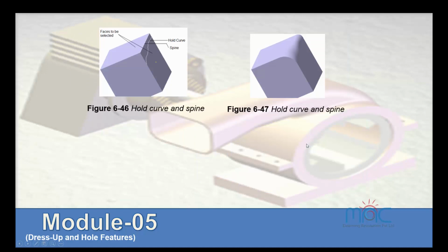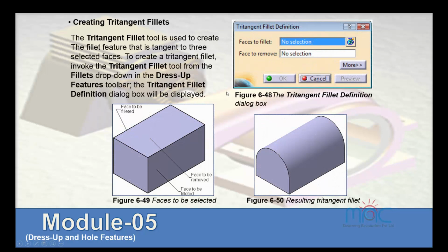And here is a little bit advanced option where the curve is the primary dominant for controlling the contour of the curve and the shape of your particular fillet. The fillet radius is controlled through the curve when that is applied. And in very typical cases, you can use it. You do not get a bunch of operations for that.